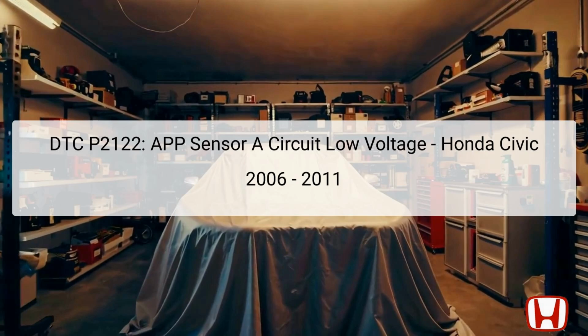Hello everyone. Today's presentation focuses on the Diagnostic Trouble Code DTC P2122, which indicates an issue with the Accelerator Pedal Position APP Sensor A, specifically relating to the Throttle Position Sensor D circuit, showing low voltage. This problem can significantly affect the vehicle's throttle response, potentially leading to reduced engine performance or even stalling under certain conditions. The Honda Civic models from 2006 to 2011 may experience this issue due to component wear or electrical faults.